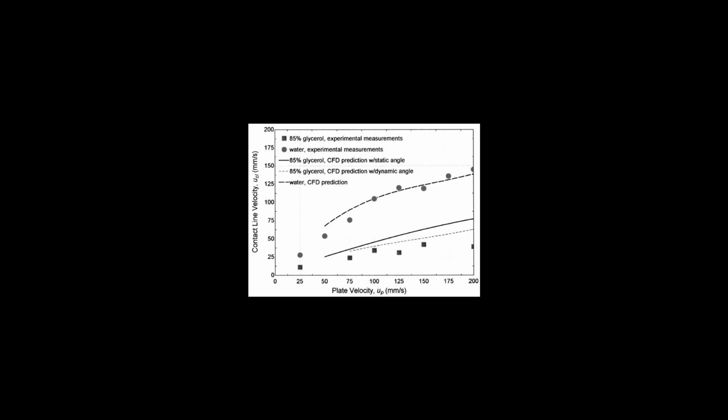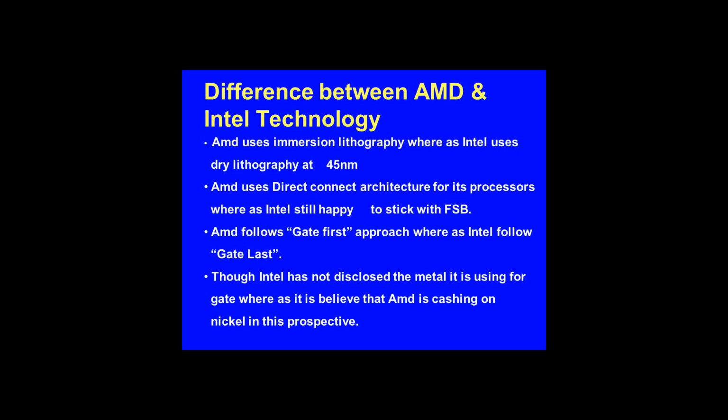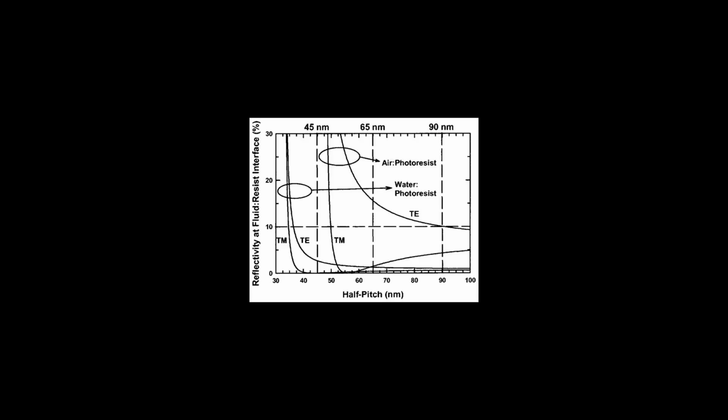Such enhancements include the use of higher refractive index materials in the final lens, immersion fluid, and photoresist, in order to improve the resolution with single patterning. Currently, the most promising high-index lens material is lutetium aluminum garnet, with a refractive index of 2.14. High-index immersion fluids are approaching refractive index values of 1.7. These new developments allow the optical resolution to approach approximately 30 nm.